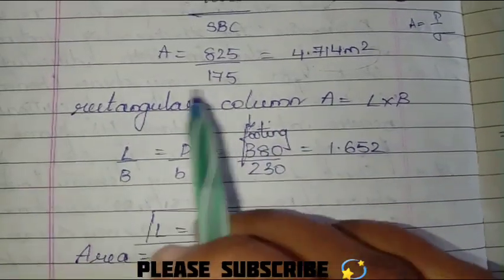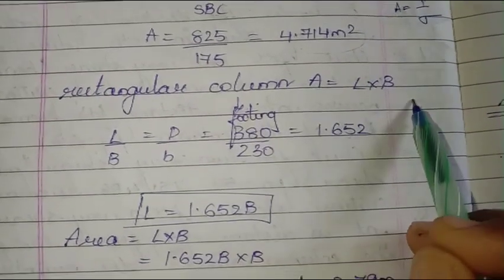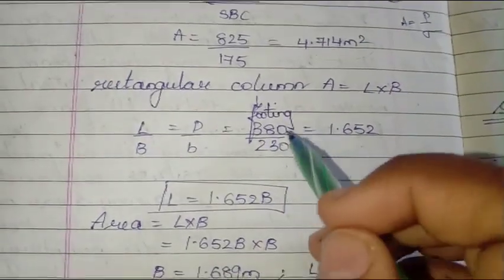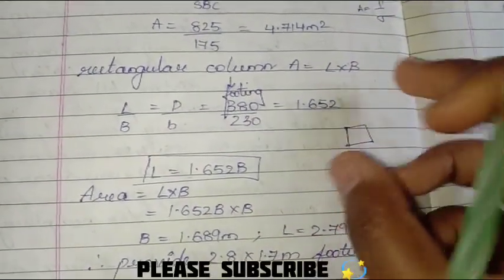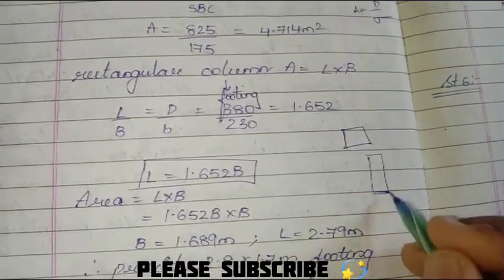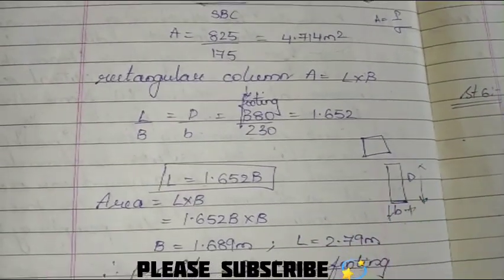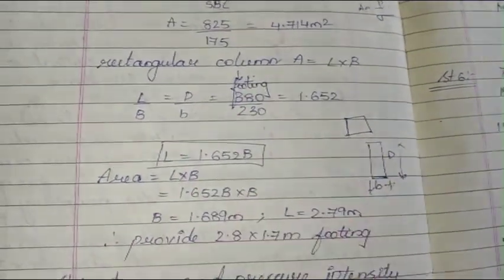As we are given the rectangular column, we are considering the rectangular footing over here. That's going to be area is equals to length into breadth. We know L by B is equals to capital D by small b. So this is nothing but the dimensions of the column. From the dimensions of the column given, we'll be calculating this. In this column, we have been given the capital D and the small b. B is nothing but the width of this. So depending upon the width to depth ratio of the column, we'll be analyzing this and we'll be getting the dimensions of the footing.